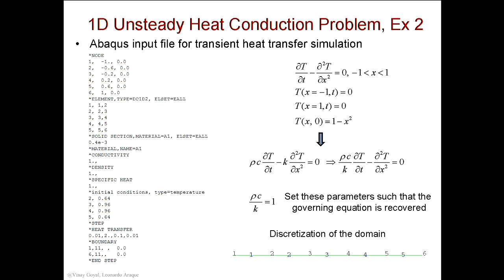All right, before I continue here, I want to point something out, because there's something exciting about Abaqus. You can actually fake Abaqus to solve non-heat transfer problems if you understand how Abaqus is doing it. Let's say I want to solve an electromechanical problem, or just come up with a problem that Abaqus doesn't solve, though I think Abaqus solves too many things, so anything I say, they probably solve it. You can fake Abaqus to use the heat transfer module to solve something else that has a partial differential equation that looks like that.